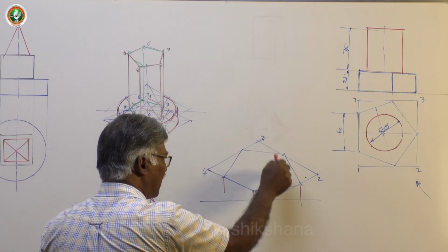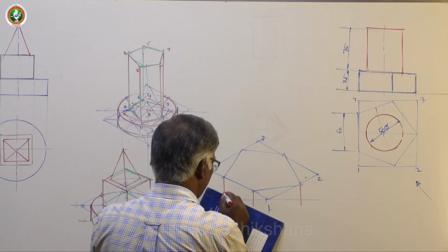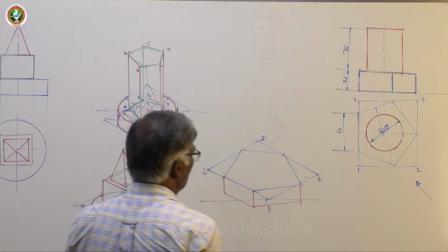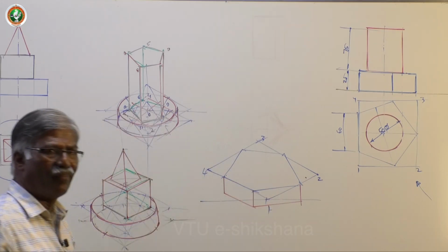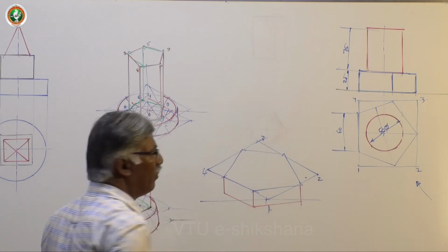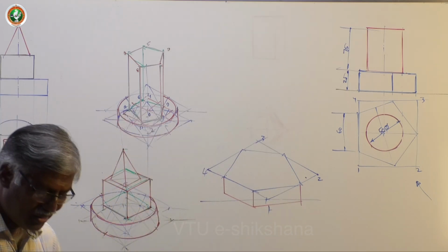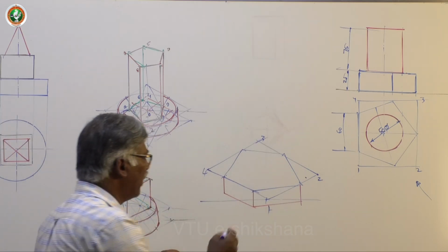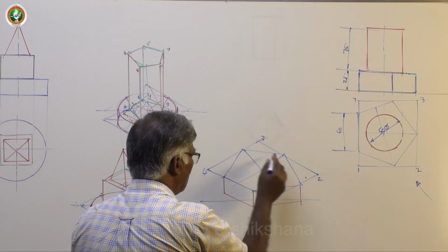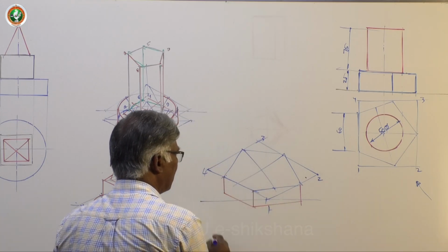You cannot draw this because it is within the solid. Now join them, equal heights, that is thickness. Now I don't want to complete this now because some portion may go behind this. Now a very simple thing, you identify the center by joining 2 medians here, this is the midpoint and this.